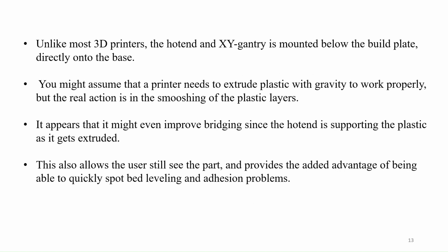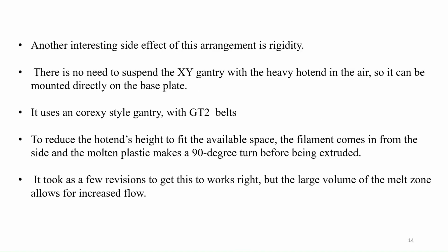Unlike most 3D printers, the hotend and the XY gantry are mounted below the build plate, directly onto the base. You might assume the printer needs to extrude the plastic with gravity to work properly, but in reality the result is smoothing of the plastic layer. It appears that it might even improve the bridging. The hotend is supported by the plastic as it is extruded. This also allows the user to still see the part, with the added advantage of being able to quickly spot bed leveling and adhesion problems.